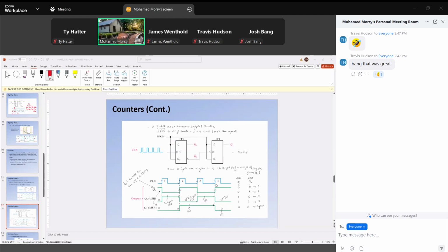So we have the clock pulse here. Immediately, we say this is a positive edge, so we put an arrow at each positive edge, meaning the variation happens at this positive edge. Leave Q0 inverted for now.